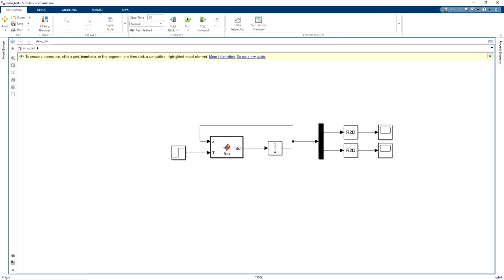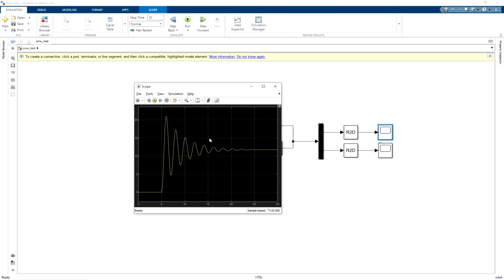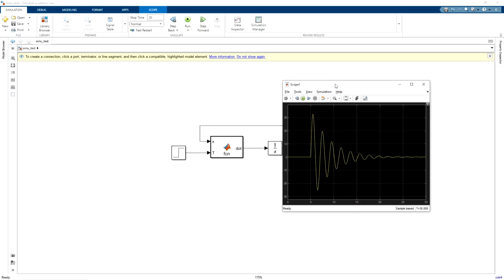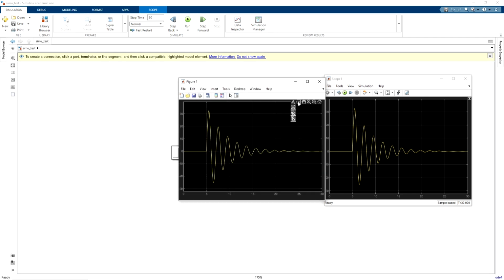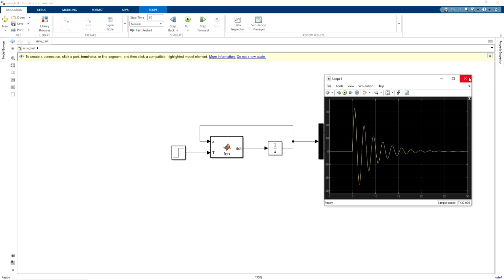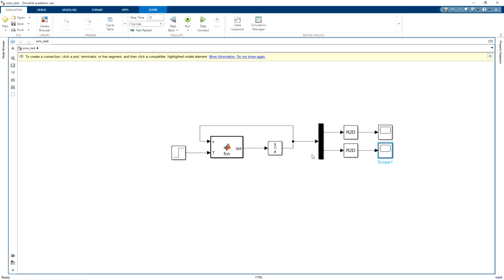It is ready. We can see it at the bottom left, and if you double click this, now we have a smoother response for angular position as well as velocity. We can go ahead with the print display to figure, and we get further options to see these data points. We can easily pan it out. You are encouraged to explore these options.